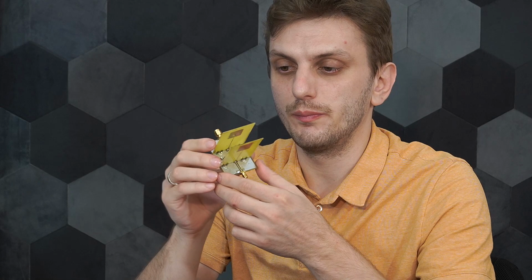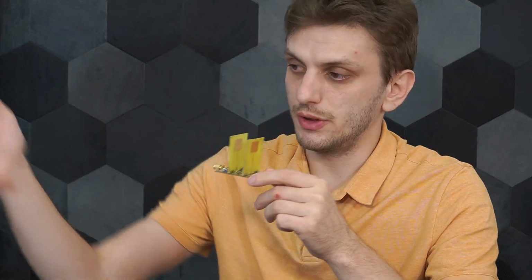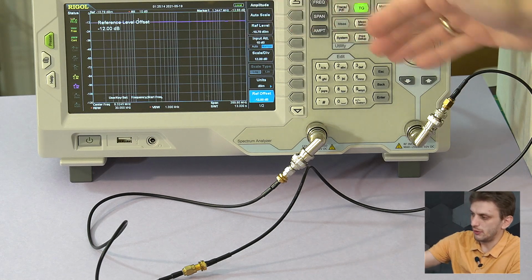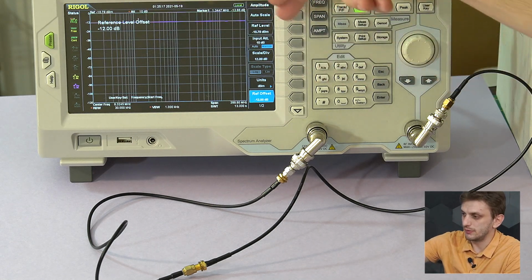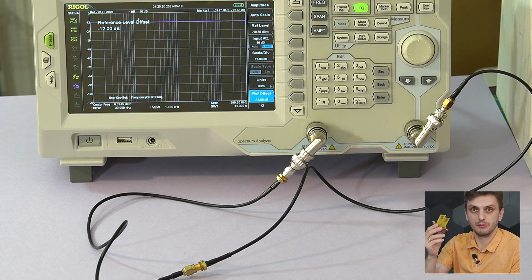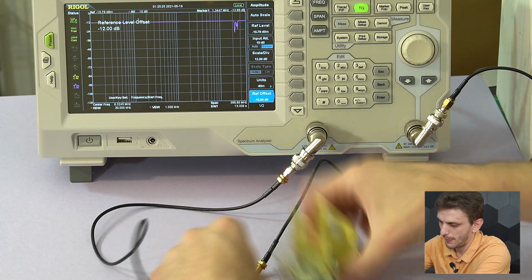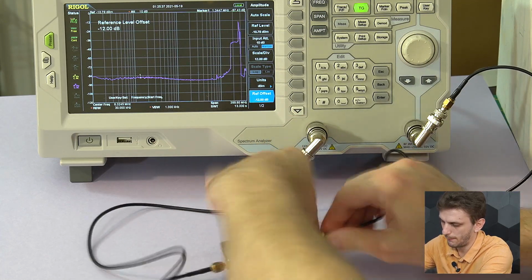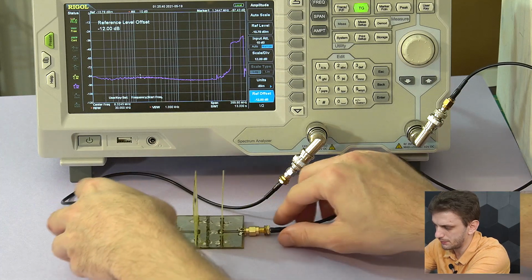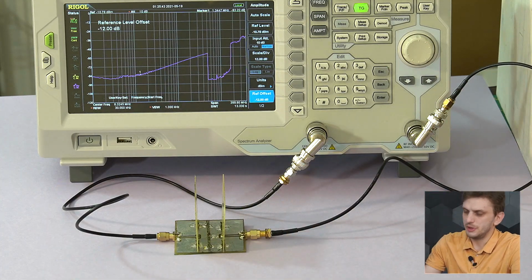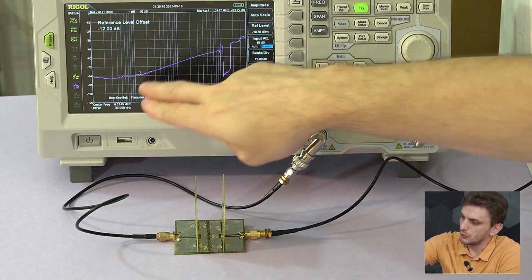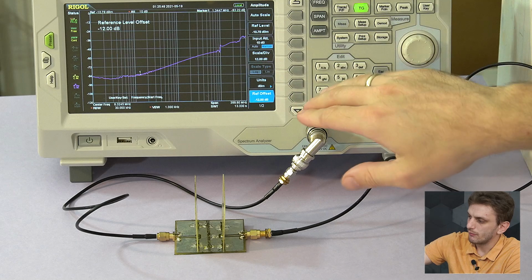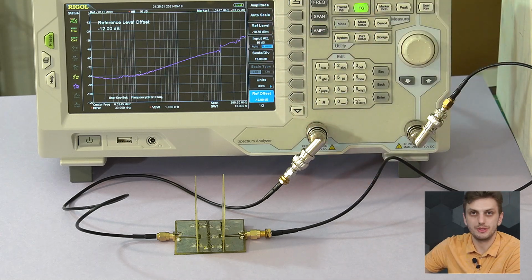So this is the setup that I will be using for today. These are two parallel plates, so printed on two PCBs and connected to SMA RF connectors. And these will be connected to the spectrum analyzer. So right now I have a normalized input running at -12 decibels, and if I plug in my board, and everything is screwed in nice and tightly, we see our clear capacitive behavior. So we see our nice rising ramp that goes higher and higher as frequency increases.